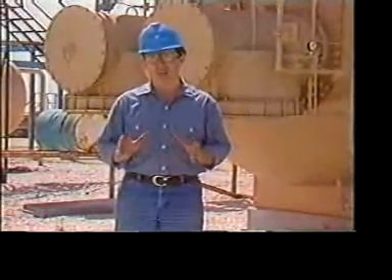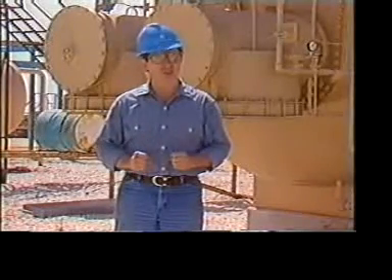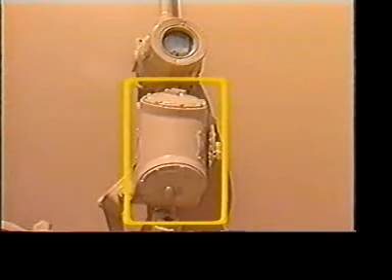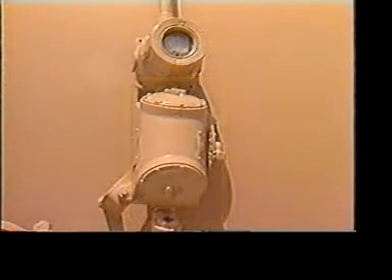The electrical system of an electrostatic treater consists of two electrical grids and a step-up transformer. The two grids are suspended one above the other in the treating section. The upper grid is grounded to the vessel shell and is adjustable so the current can be regulated to meet varying requirements. The lower grid is not grounded and receives the output from the transformer. The transformer is the heart of the electrical system. A circuit breaker located between the power source and the transformer protects the transformer from electrical power failures. A fused disconnect at the power source is recommended for maximum safety.